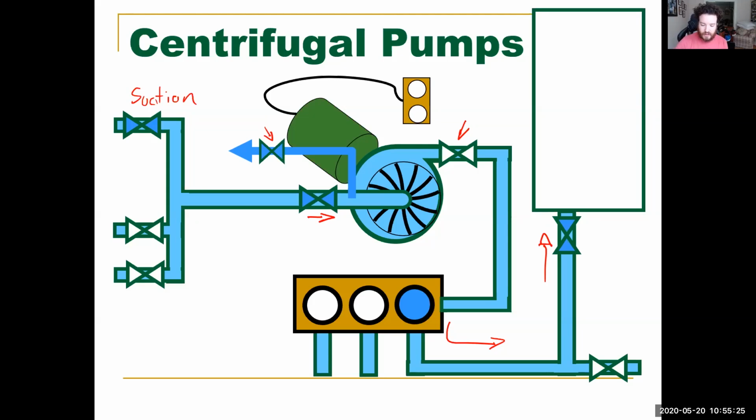Okay. Now, if this is a pump that is operated continuously, you stop it for some general maintenance, whether you're taking some readings on the electrical part of the motor, which we get into when you get into your second class cruise of what you'll have to do for that. But if you're going to be taking some readings that need it turned off, you don't really have to worry about priming. It will still be primed. But if it's been a time where you haven't used it, you're going to have to prime the pump.